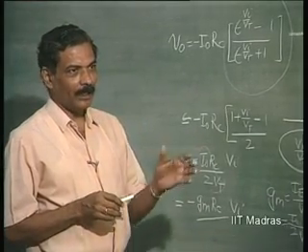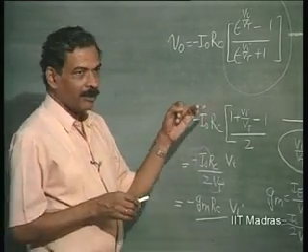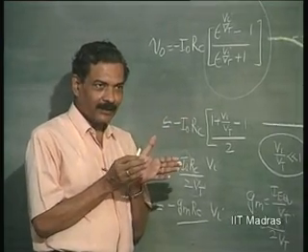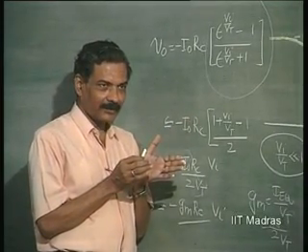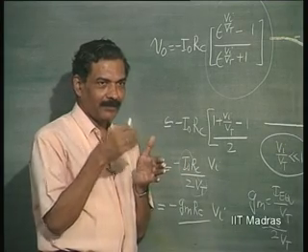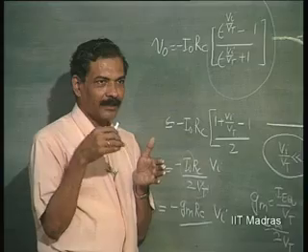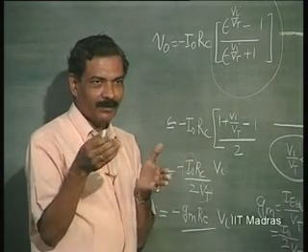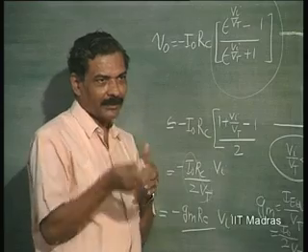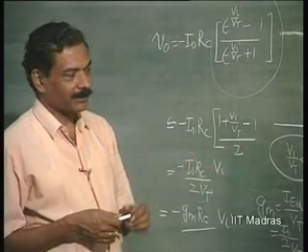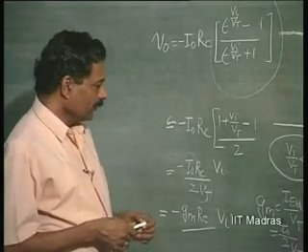Why? This is because they get cancelled with one another. These square terms, Vi by Vt whole squared and Vi by Vt to the power 4, all these things, and then you get cubic and fifth order like that. It is an odd function.